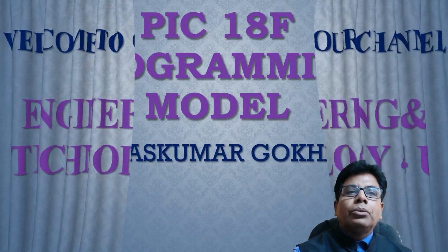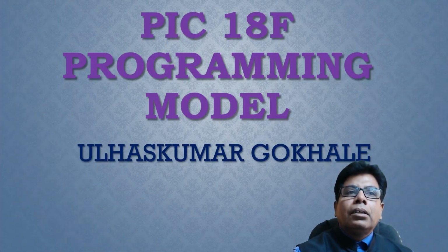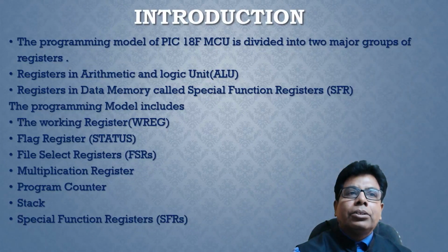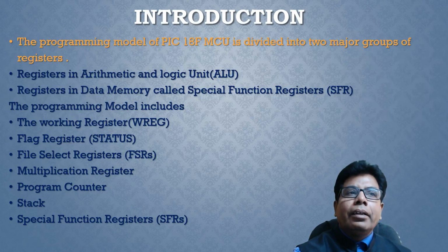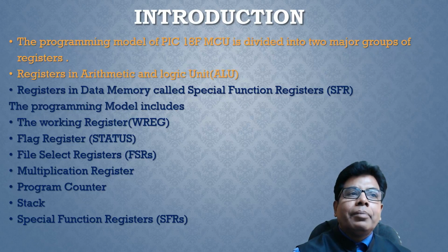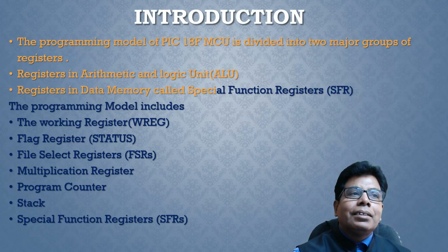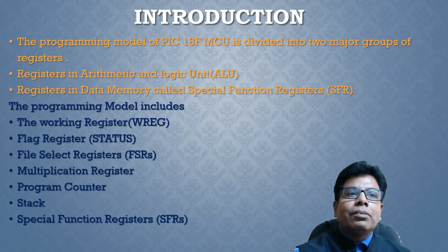In today's video, we will learn about the PIC 18 family programming model. Let us start with the introduction. The programming model of PIC 18F MCU is divided into two major groups of registers: registers in the arithmetic and logic unit, that is ALU, and the registers in data memory called the special function registers, SFRs.